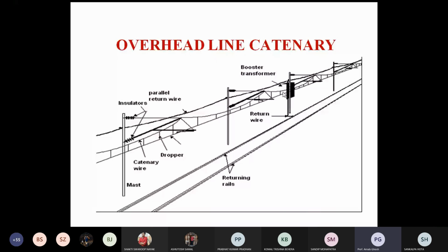All the time we talk about kilowatts or HP, which relate to active power rating, not reactive power rating. But in the case of a generator, we say something like a 5 MVA generator having 0.9 power factor. Since field excitation is there, power factor is definitely important for the generator.